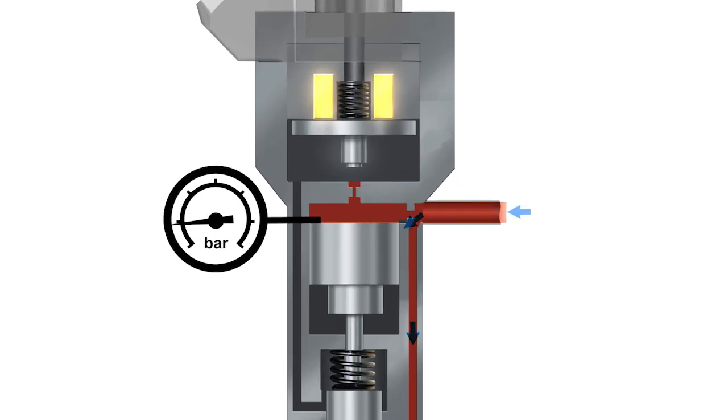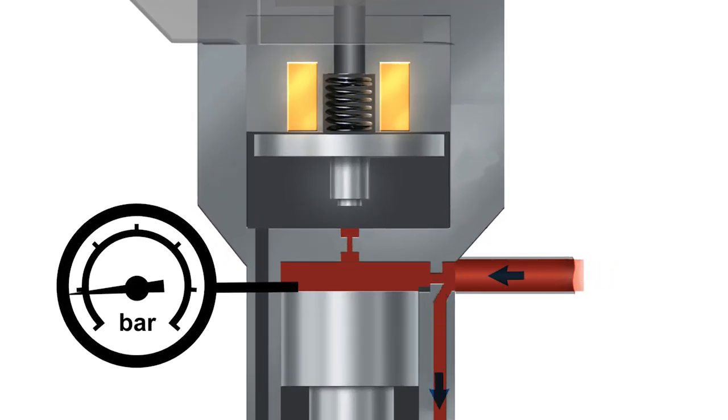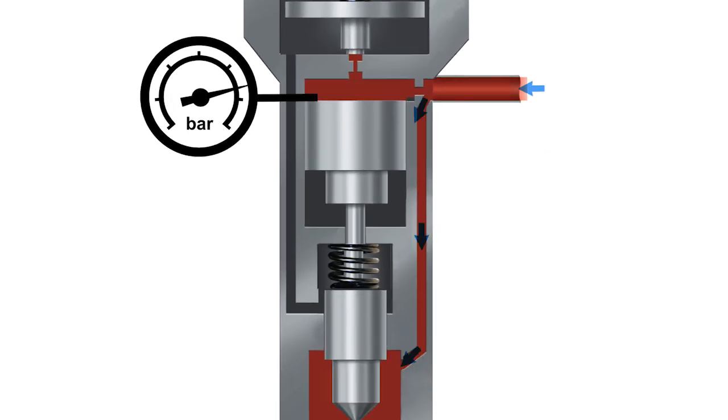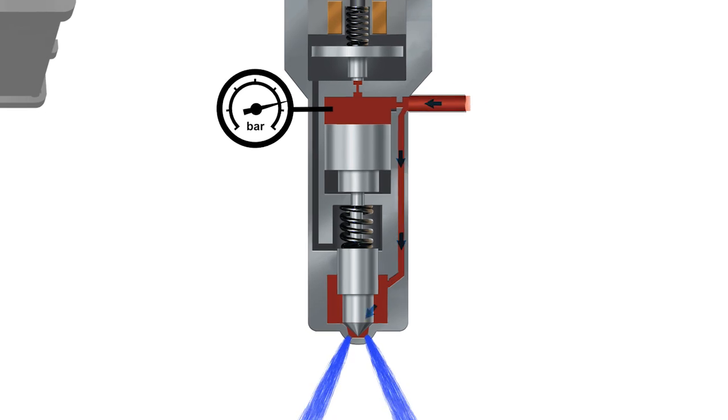To close the injector, the solenoid is de-energised. The two-way valve will now close. Fuel pressure will now build up above the command piston. This force, combined with the force of the needle return spring, will cause the needle to reseat, blocking the flow of fuel.